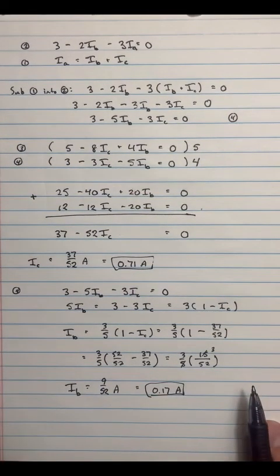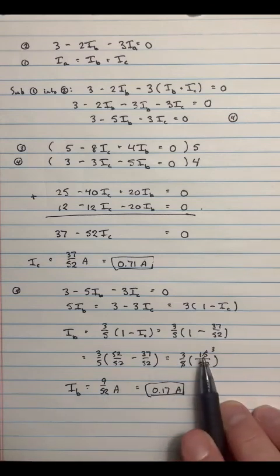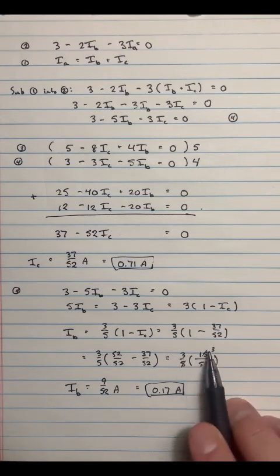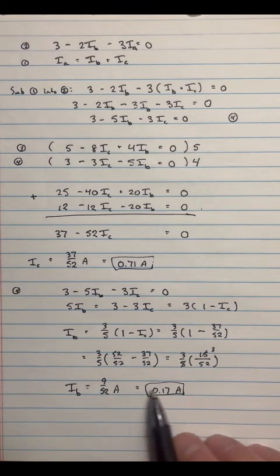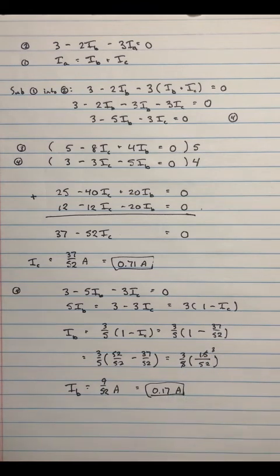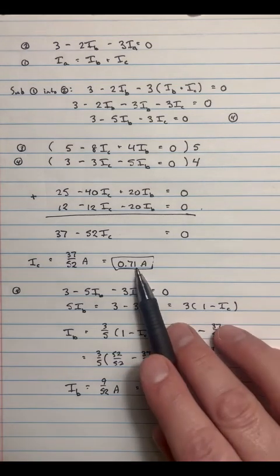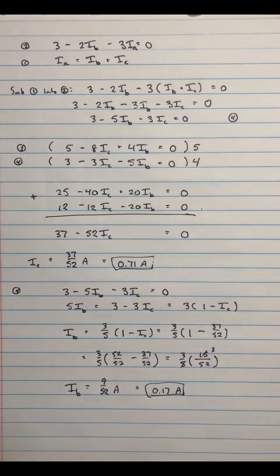Okay, I had to do a quick adjustment. We're back. So if we do this calculation, we get the 15 and 5 cancel each other. 3 times 3 is 9, 9/52 amps, 0.17 amps. By the way, notice something that's happened. I managed to guess right, it turns out. Both of these numbers are positive currents, which means the arrows I drew are in the correct directions. But again, if I hadn't guessed correctly, one of those numbers, or possibly both of them, would have been negative, and all that would have meant is that the current was flowing in the other direction.